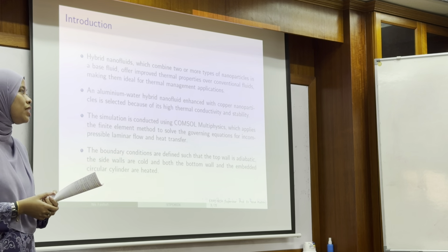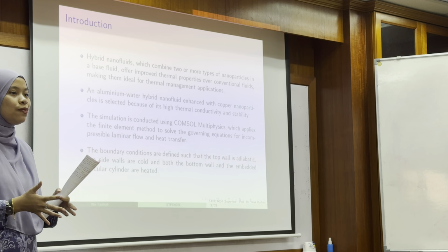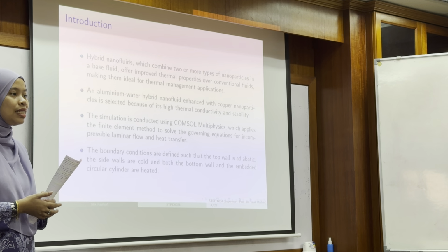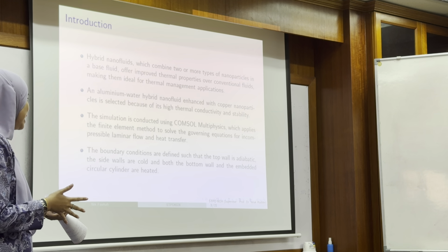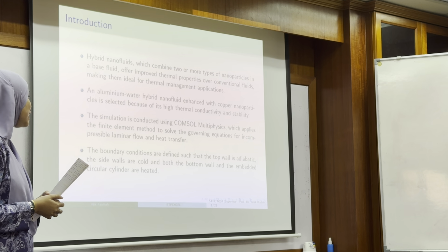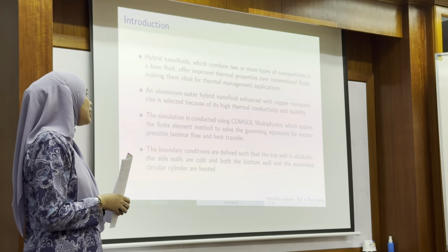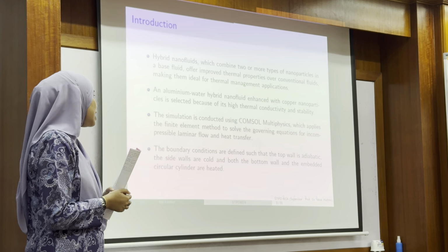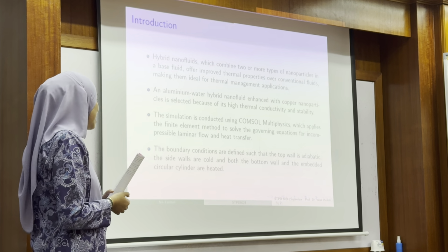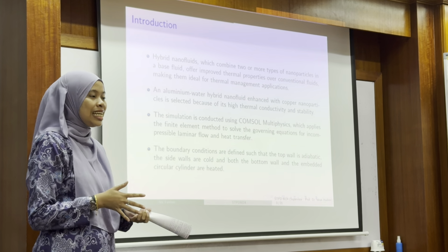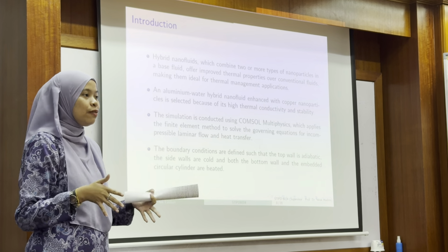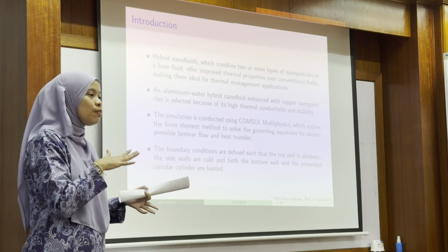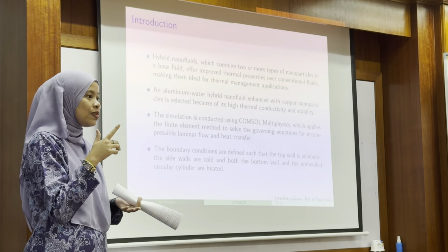So in this study, I have chosen the aluminium water hybrid nanofluid enhanced with copper nanoparticle because of its high thermal conductivity and stability. And the simulation is conducted using the software COMSOL Multiphysics, which applies the finite element method to solve the governing equation for the incompressible laminar flow and heat transfer. And the boundary conditions are defined such that the top wall is adiabatic, the side walls of the cavity are cooled, and the bottom wall of the cavity and the embedded circular cylinder are heated.